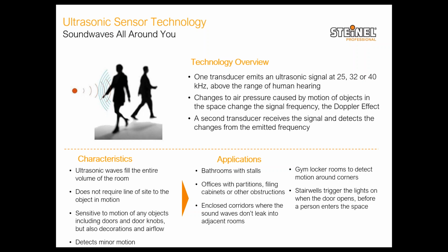I remember we had a project in my previous company where we were using ultrasonic sensors, and there was one corner that would never go off. The lights would never go off. After a bit of investigation, we found out that behind that particular wall, there's a pump room. So every time these pumps turned on, that wall would start vibrating, and our ultrasonic sensor would just keep the lights on.